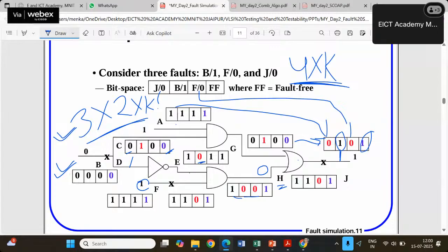This is a single fault, and for this single fault I need to make one more pass. So if we have 2 passes, it has to be multiplied by 2. If we need 3 passes, then you have to multiply it by 3, and so on. So this is underutilization of the complete set of memory elements.